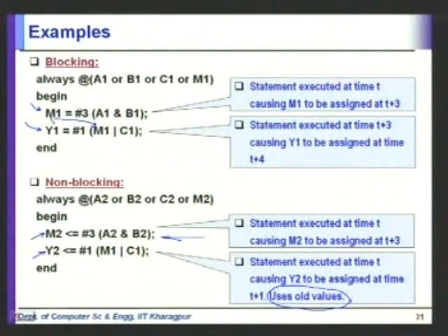Okay, that's clear enough. Now where does the non-blocking business come in? The non-blocking business is different because when I am processing active events like these, for blocking cases I cannot move into the next procedural statement until I have completed the one. That is the meaning of blocking assignment. So I cannot even reach here until the previous assignment has been completed.